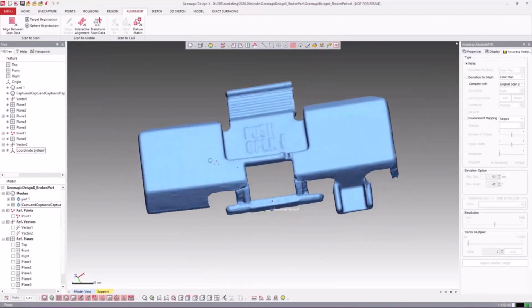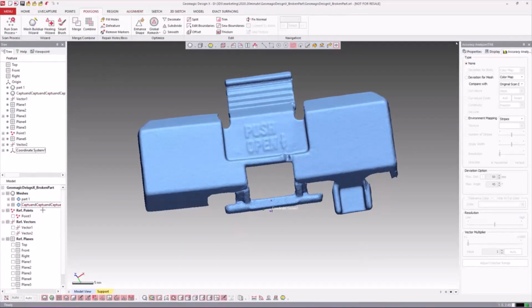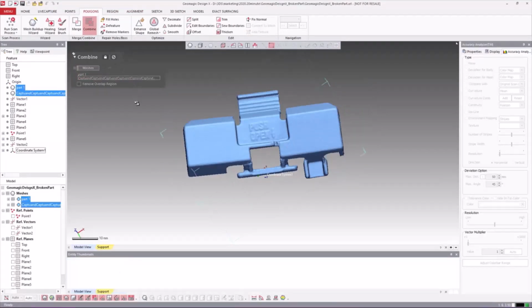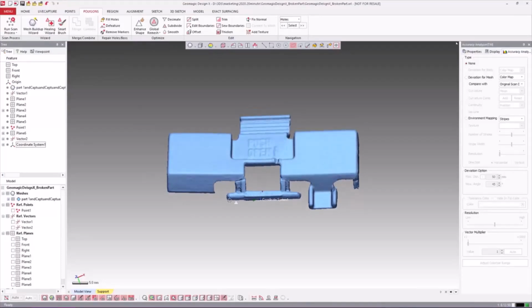And then now what I'm going to do is, because I really don't want to move this thing, I think it's good enough. I'm just going to lock these together. So I'm just going to come into my polygon tools here, hit combine, and lock my meshes, create a single one. So we could leave them as two, and we could model things individually and then correct from there.